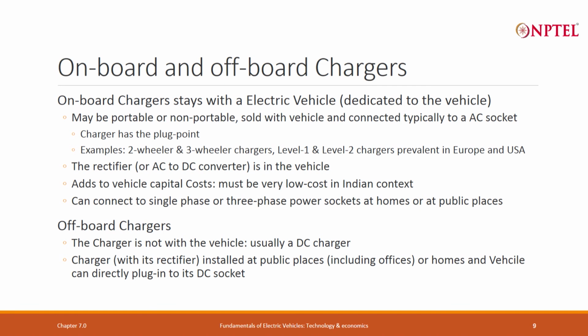Two-wheeler and three-wheeler chargers with level 1 and 2 chargers are prevalent in Europe and United States. Here, since AC is the input, the rectifier is in the vehicle, in the onboard charger. It adds to the vehicle cost, but if it is a low kilowatt charger, it does not add too much. It must be very low cost in the Indian market. We will look at this in the end. It can connect to a single phase or three phase depending on the amount of current drawn, or power sockets at homes and public places. So, this is the on-board charger.